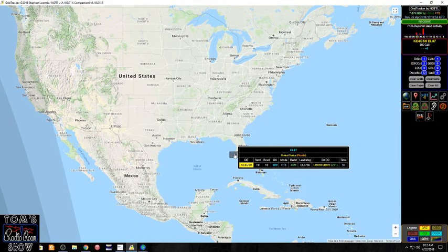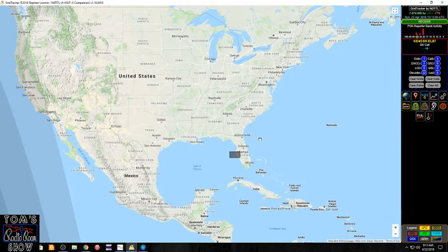Now, this is my location and my call sign, KE4GSK, and I can only receive on these bands except the 10-meter band, and that's what I want to use this to monitor, the 10-meter band. And right now I'm just monitoring the 40-meter band, because it's more active and more likely that I'll receive messages. I guess there is a period of time at which it clears the data. And since I have turned off the audio out of SDR Uno, it's not getting any new data.